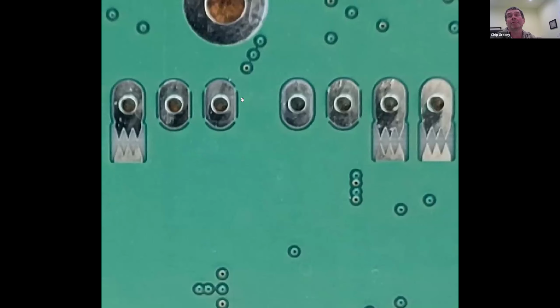I didn't have lots of room, but I think this should be sufficient for what we'd be looking at anyway. But the crazy thing in PLCs, you don't just have to worry about this. You have to worry about them completely screwing wires into the wrong places. So even the 24-volt outputs are fused with half-amp PTCs. So if they just connect 24 volts to ground, the world doesn't end.